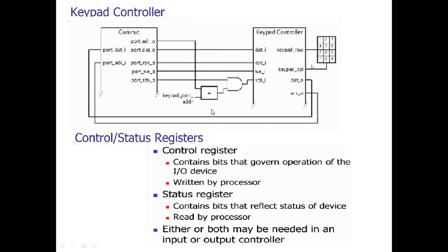So you can find here greater than one number of ports for interfacing in the command processor. Both inputs to the AND gate, what you are seeing here, are equal. Then this keypad controller will be activated. Why? Because we know the basic property of an AND gate: when all the inputs to the AND gate are high, then only the output will be high.